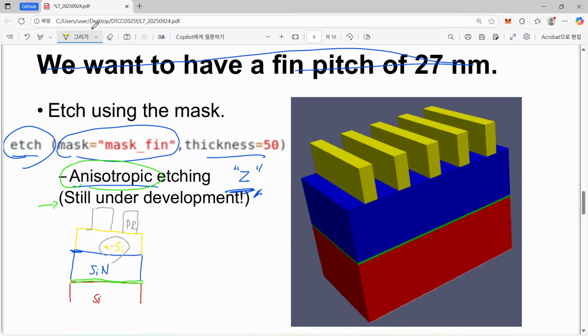And in this etching process, we prefer to have anisotropic etching. So selectively etching only amorphous silicon and not etching silicon nitride, after this action, now we have a certain structure that looks like this. This is the one you are looking at in these graphs.